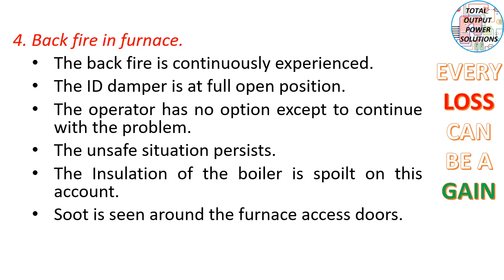Then there is backfire in the furnace. The backfire is continuously experienced. The ID fan damper is at full open position. The operator has no option except to continue with the problem. This unsafe condition persists. The insulation of the boiler is spoiled on this account. Soot is seen around the furnace access doors.